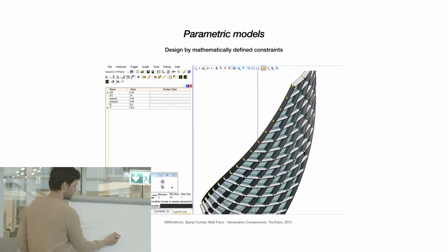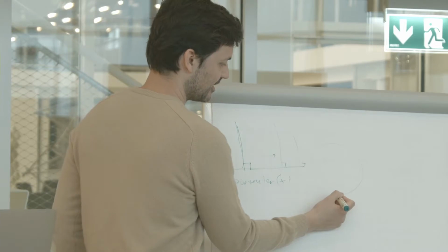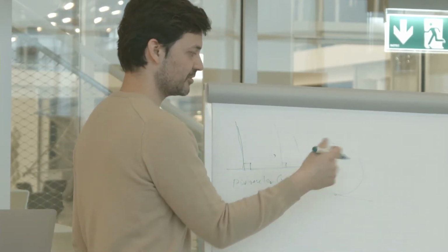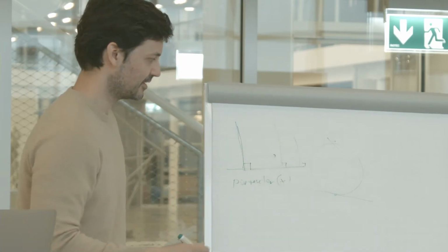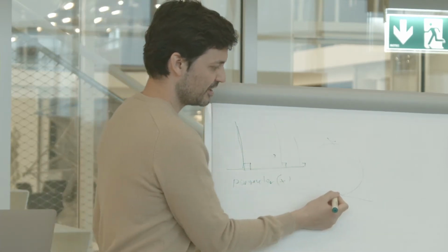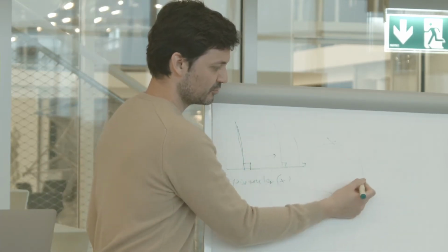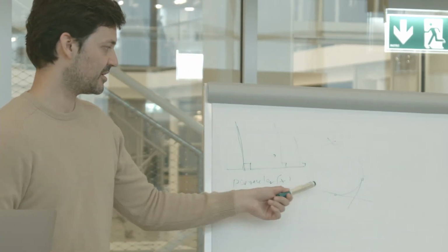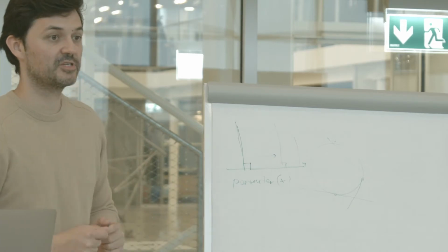Or when you draw a circle, you say that the line you want to draw must be a tangent. So if you try to draw a line like this, it will not allow you. It will say illegal move. You will only be able to move the line on a circle. So there's a parameter which describes this relation. And this is what is called constraints, yeah?